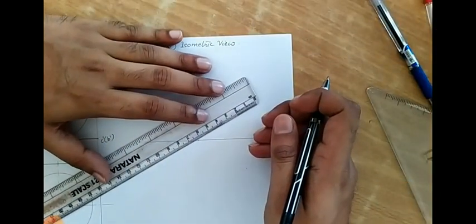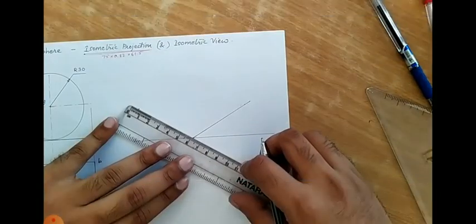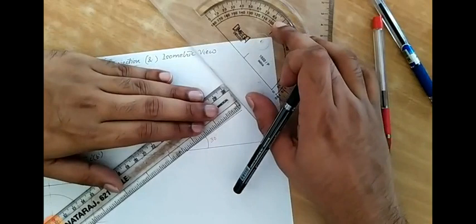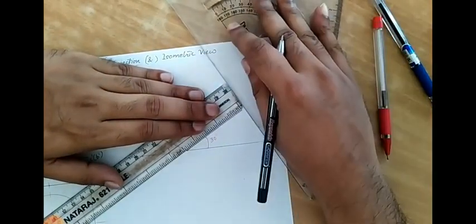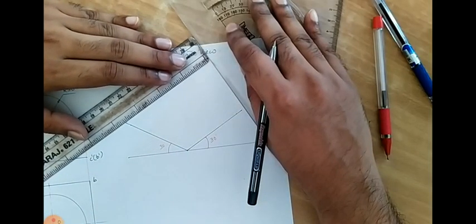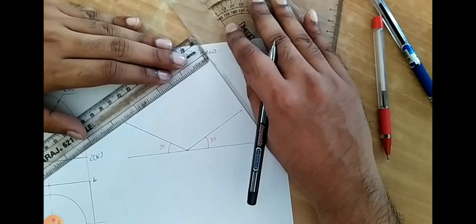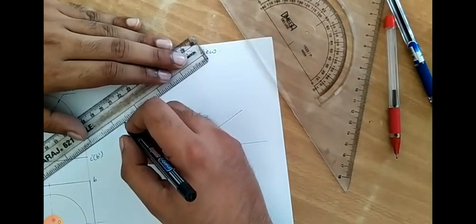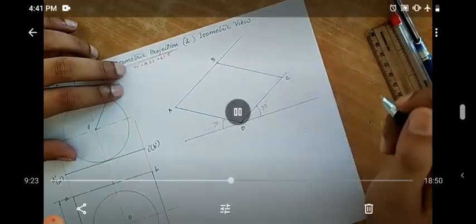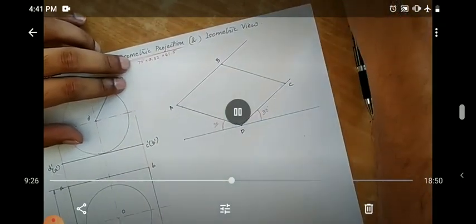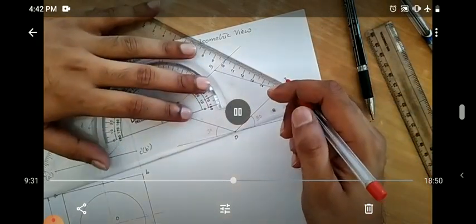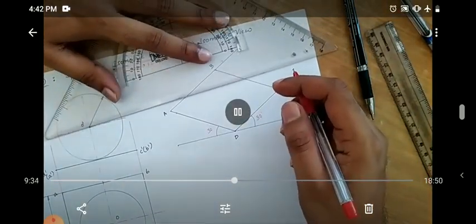Hence, the distance of that particular side is multiplied by 0.82. That means 75 into 0.82. I am marking the isometric projection of the square first, square plate first, so it will look like a rhombus. And now the edges of that square will have the length equal to 75 into 0.82. See, 75 into 0.82, you can clearly see at the top of the video. 75 into 0.82 is equal to 61.5. The value is taken as 61.5. Now I am locating the center of the rhombus.